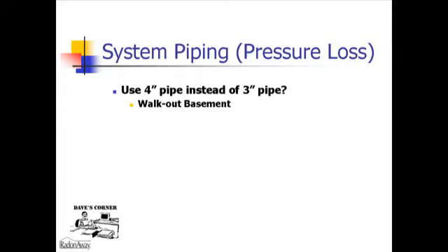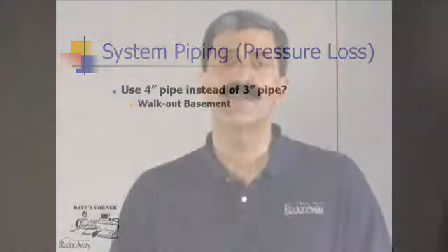When might those situations arise in a residential mitigation system? If you have a walkout basement, because the foundation footer is buried less deep than it would be in a fully buried basement, they tend to have more airflow leakage around the foundation. So your airflows, and consequently your driving forces, which might be caused by the wind underneath the slab, require that you move larger volumes of air than you typically would in a residential situation.